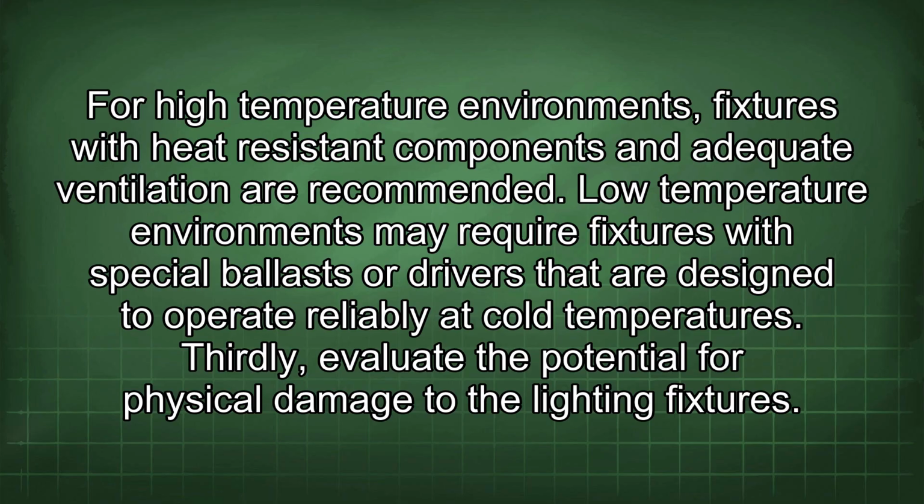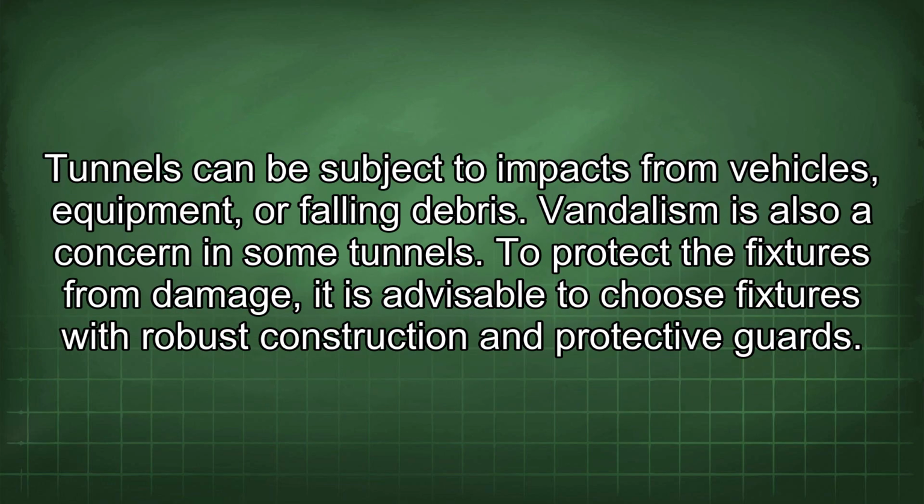Thirdly, evaluate the potential for physical damage to the lighting fixtures. Tunnels can be subject to impacts from vehicles, equipment, or falling debris. Vandalism is also a concern in some tunnels. To protect the fixtures from damage, it is advisable to choose fixtures with robust construction and protective guards.